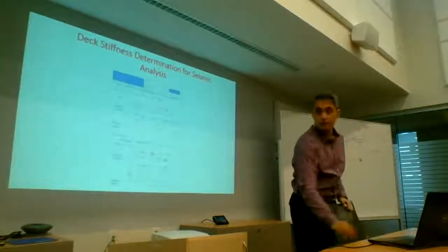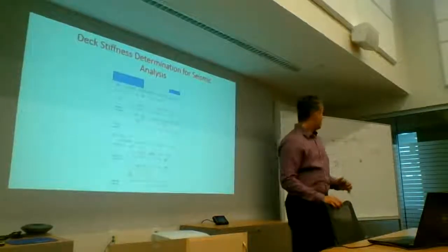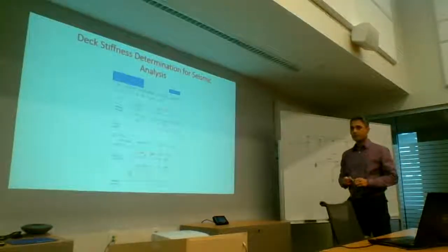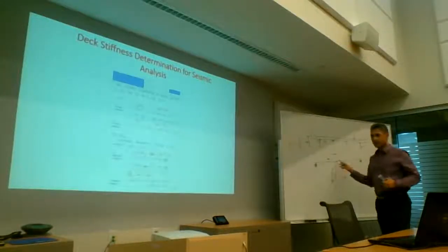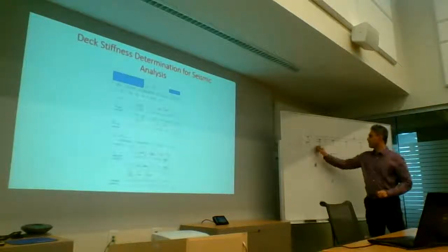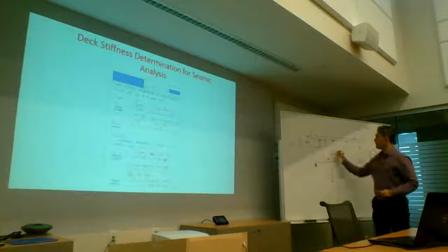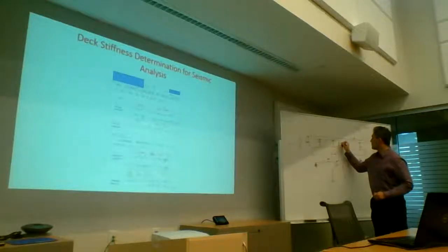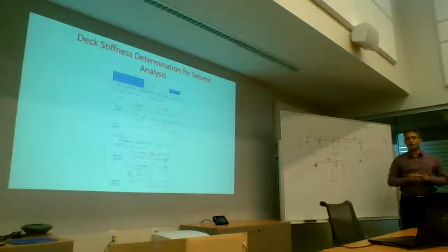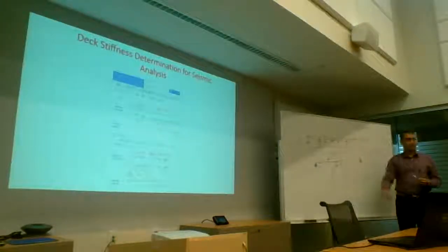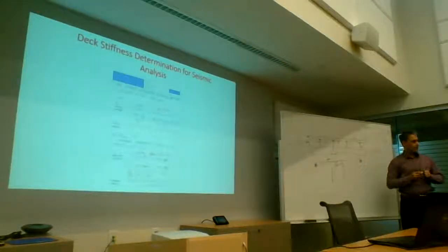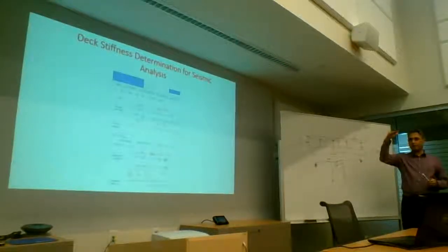And what are the properties of this vertical stick? Those are the properties we're trying to calculate. Yes, that is for the horizontal one, but the vertical stick is just a rigid element. Because when you're making this sit on top of a cap beam, you have this artificial stick that takes you to the CG of the deck. So what you're doing is you're just putting a rigid offset here to capture the appropriate CG,